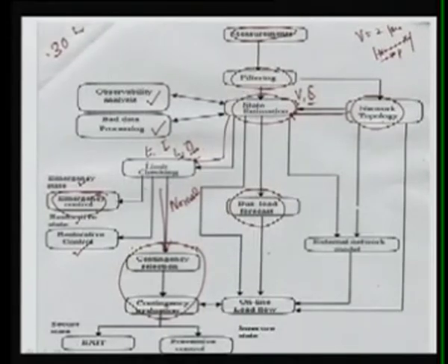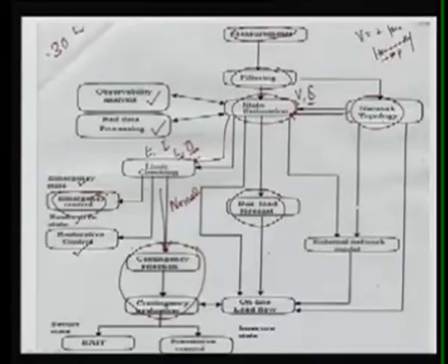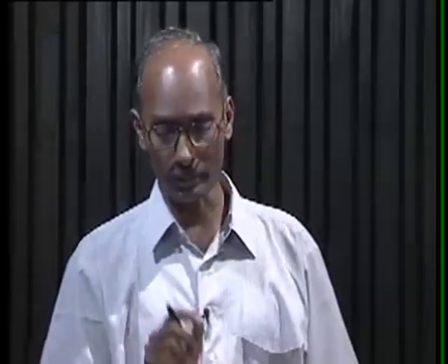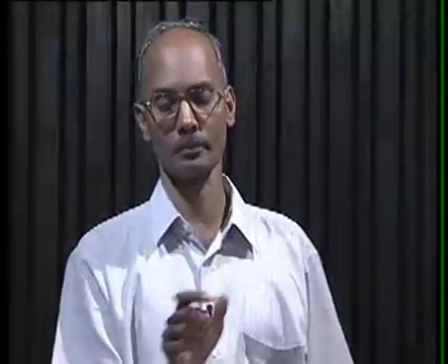So every half an hour we get data from the RTUs, and finally we do all this process, and again after half an hour we get a new set of data. In this half an hour, your load keeps changing and will be varying. So we require the load forecast during that period so that we can have the exact information about the system state within this half an hour.